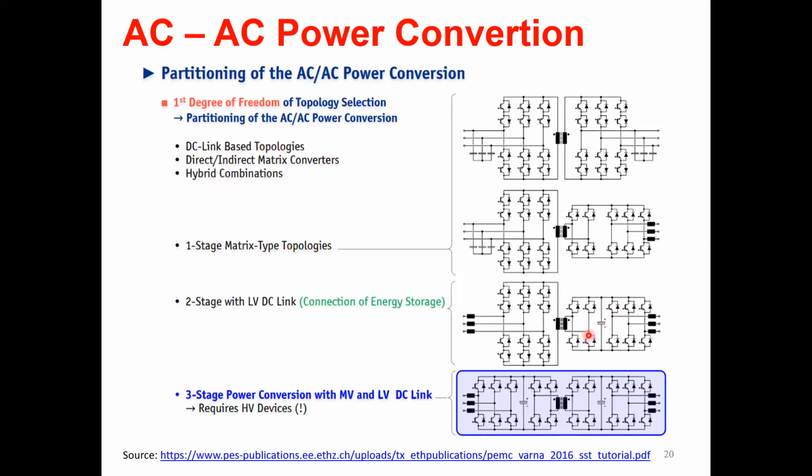So you have to design this capacitor in such a way that the switching frequency current mainly passes through this capacitor and doesn't produce a lot of voltage pulsation of that frequency in this DC bus. All you have to use is V equals I times Z, where Z equals 1 over omega C. In this case, omega will depend on the switching frequency of this converter. I hope that answers your question.